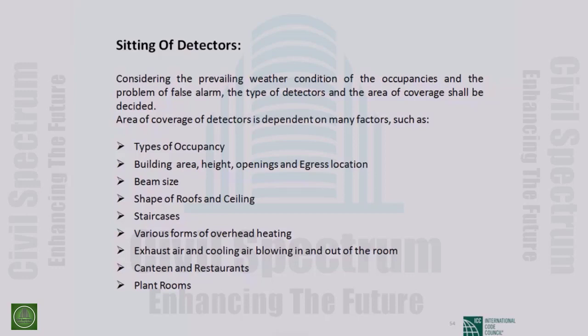Every manufacturer has their own suggestions, but you have to think about your egress system, particularly on a stair or lift. These are the areas where you put a special detector. There is every chance that the exhaust air flow and cooling air create obstruction for detection. So you have to be very careful about keeping the detector at the proper location.